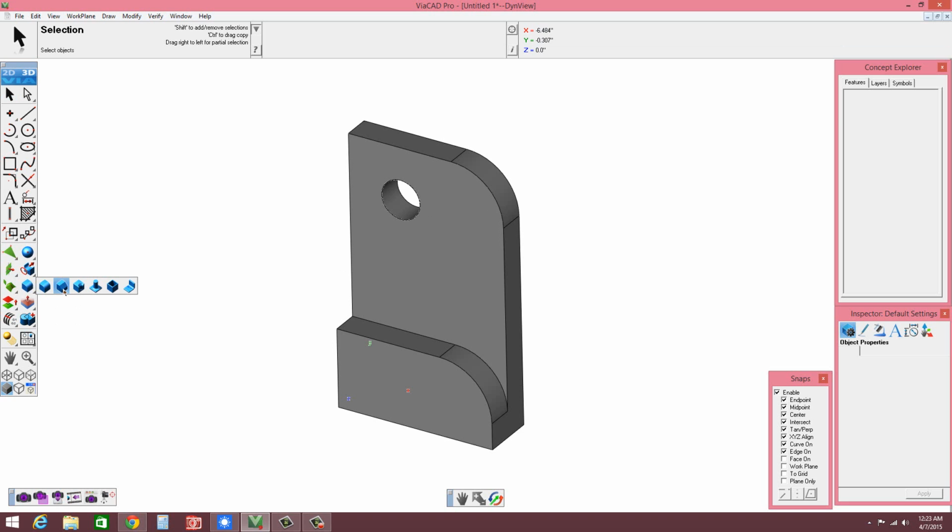Okay, now let's go ahead and we'll go with chamfer. Okay, and for the chamfer, we could set it to 2 lengths, length and angle, vertex to chamfer. If we go currently, we could go to length and angle. We'll set it at 45 degrees. That way it'll be equal on both sides. And we could keep it at, we'll actually make it 0.25. And now you could go ahead and select the edges.